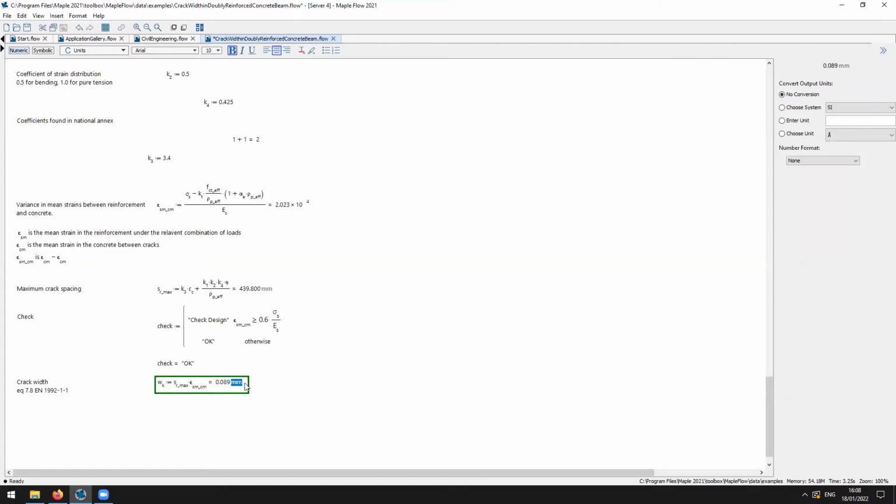So now my focus is in this result, and I've expanded the context panel, and this allows me to rescale the unit to something else. So let's say I wanted to rescale this to inches. I can pick from a series of predefined units in here. So that's in inches, or I can type in a custom unit in here as well. Let's add in some numeric formatting as well. Let's change that to a scientific format.